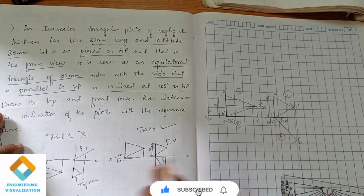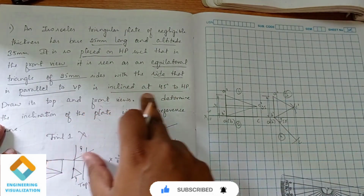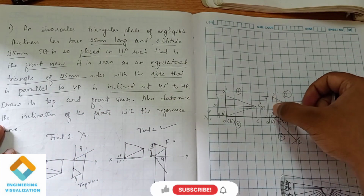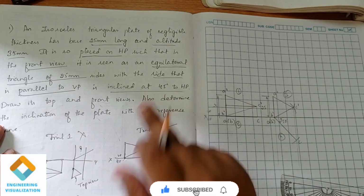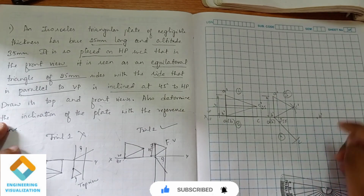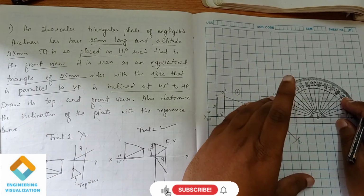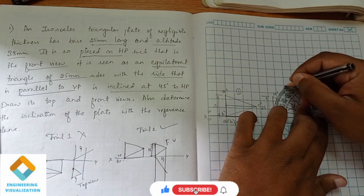Now fifth. You can see in this question, the side that is parallel to VP is inclined at 45 degrees. So this is A dash, B dash, and this is what is parallel to the VP. Now we have to incline this end by an angle of 45 degrees. So how do we do that? So here we are marking a point of B dash. Here at this point I will be taking an angle of 45 degrees.